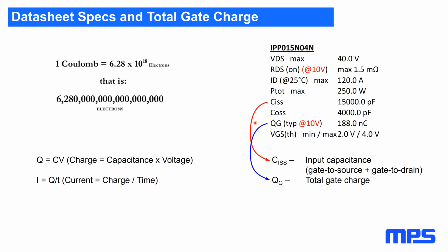And next, what's the max speed commercial MOSFETs can switch at? There are different types of MOSFETs for different applications. There are MOSFETs designed for RF amplifiers that can run up to maybe a gigahertz or something like that. For the switching MOSFETs like we're talking about here, I don't know offhand, but you can certainly get to several megahertz, if not tens of megahertz.